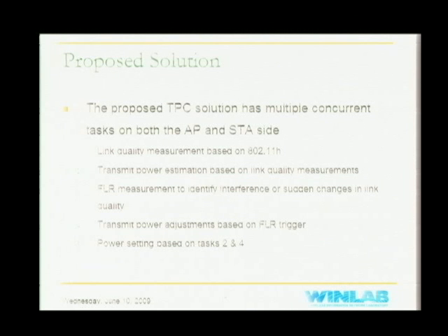On the other hand, in the opposite carrier sense situation, by lowering our powers we can maintain the same SINR but operate below the carrier sense threshold. Then we can transmit in parallel and double the capacity.